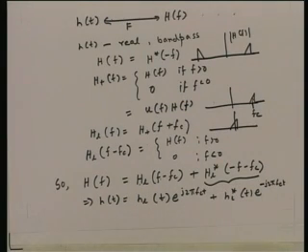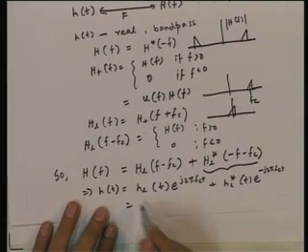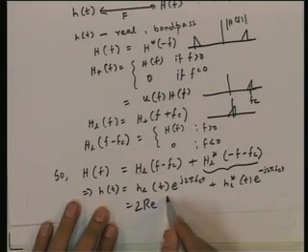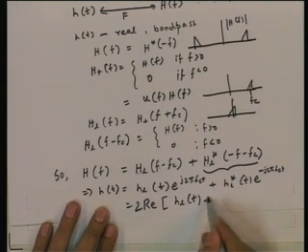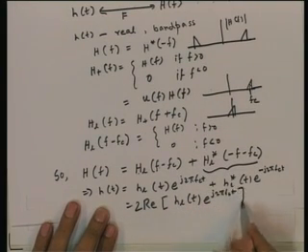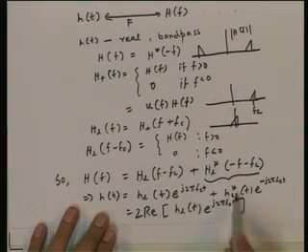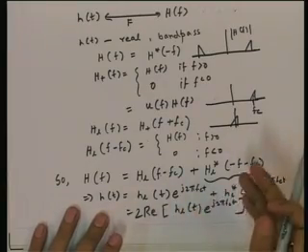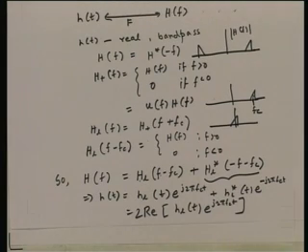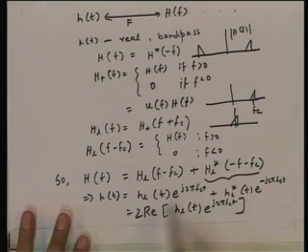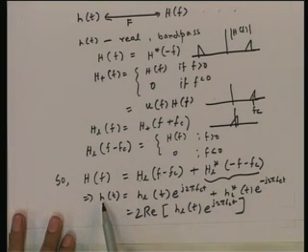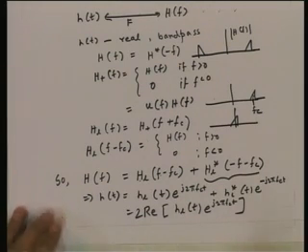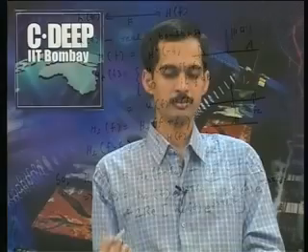Similarly here. Now this can also be written as 2 times the real part of h_L(t) e^{j2πf_c t}. This is because this part is the conjugate of this part, so only the real parts will remain, and the imaginary parts will cancel. So this is what we have. The actual impulse response is expressed in terms of the low pass equivalent of the impulse response. This is what we also did in the representation of band pass signals, and we have done the same thing again for band pass systems.